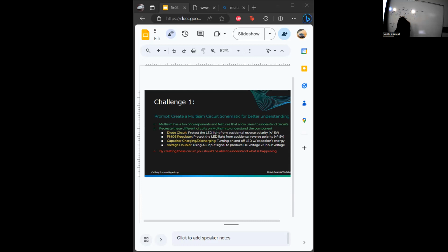That means that this sign is now flipped, like that, right? So using that same battery concept, this is 5 volts. This is 4.3 volts, right? That means that at this point, right now, this should be 9.3 volts, right? Because the batteries are put together like this.